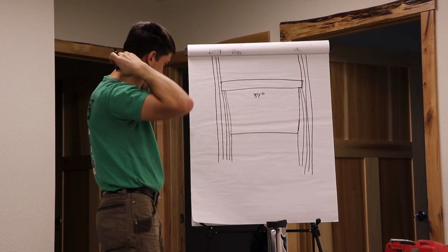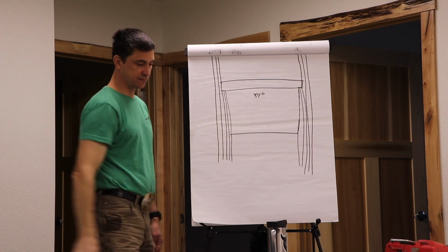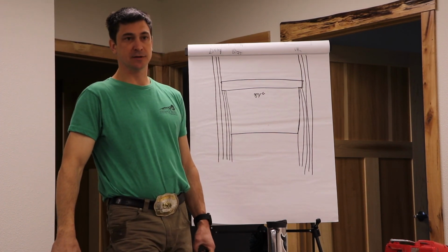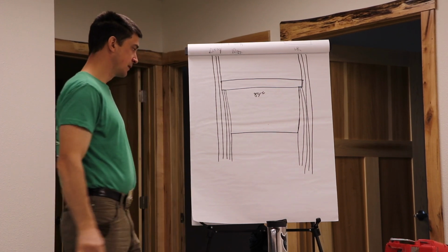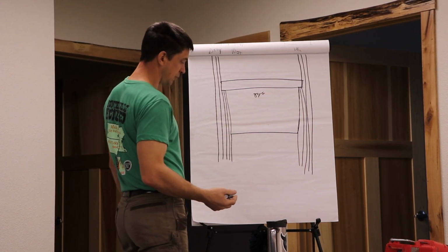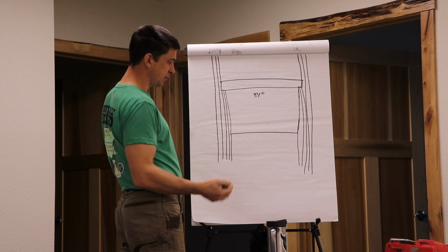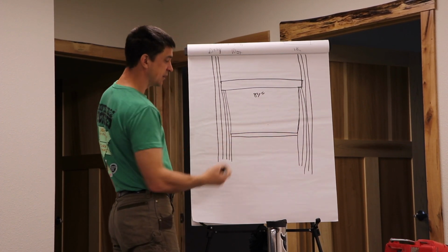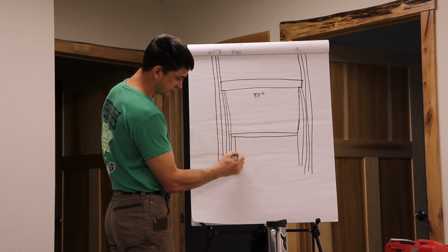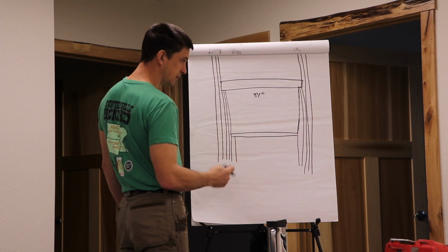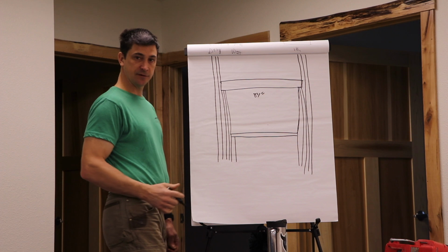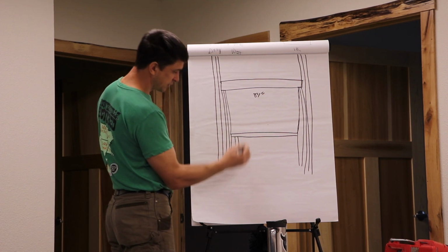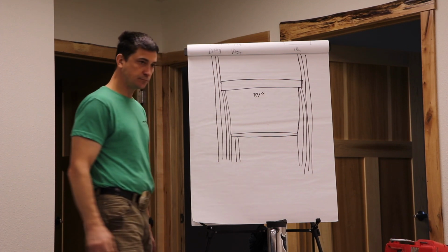So now, down here we've got 4 pieces of framing. Does anybody know how thick that's going to be? 6 inches. 6 inches, okay? Then, our wonderful, ambitious framer says, ooh, I gotta support the end of this sill. So we're gonna slap another one in here, okay? So now we're 7.5 inches. And then, our layout comes right here, so we're gonna put another one there.